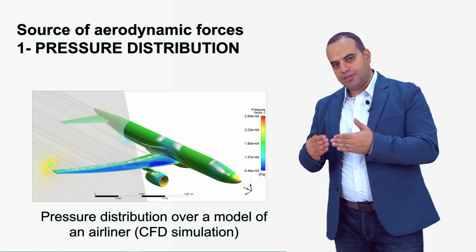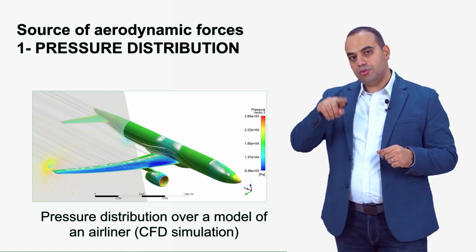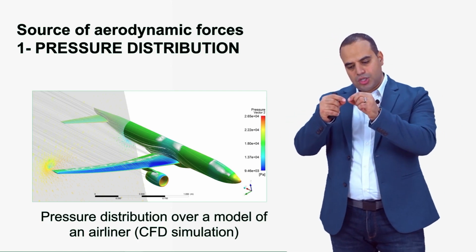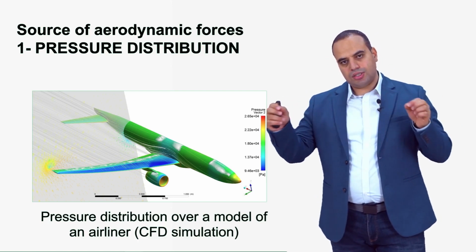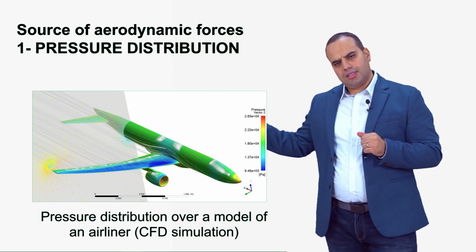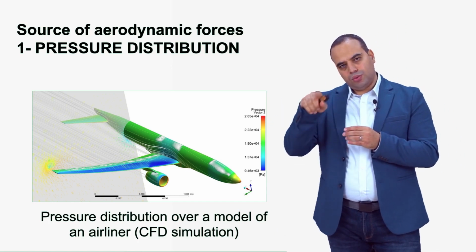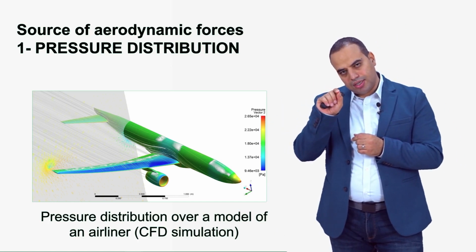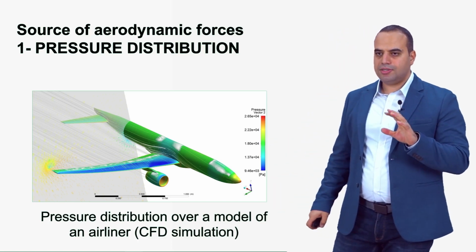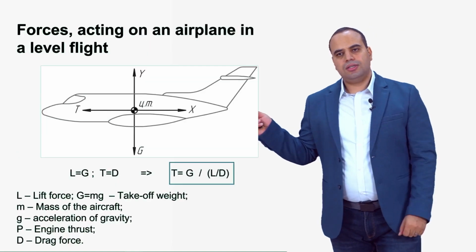Because it has to do with the lift, right? The lift induces the wingtip vortex, so the lift causes the wingtip vortex, and the wingtip vortex causes low pressure in its core, and low pressure in its core causes drag, right? It prevents the aircraft from moving forward, and this is clearly visible from this picture. Behind the aircraft, we have the vortex, and we have the tip at the core. Inside the center of the vortex, we have a blue low pressure, right? And that means drag, right? So that's the second source here, which is called induced drag, right?